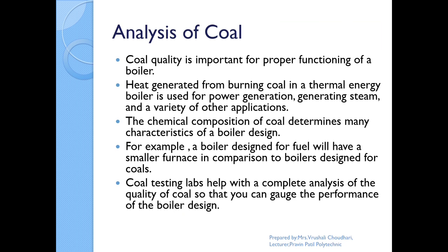Coal quality is important for the proper functioning of a boiler. Heat generated from burning coal is thermal energy. A boiler is used for power generation, generating steam. The chemical composition of coal determines characteristics of the boiler, such as the boiler design. If the boiler is designed for fuel oil, we have to use a smaller furnace in comparison to a boiler designed for coal. Coal testing labs are necessary to understand the quality of coal and how much moisture and how much pollution can be produced by this coal.